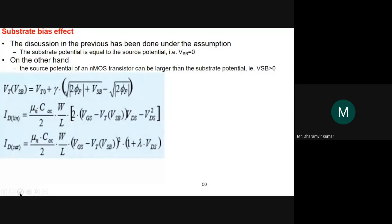So this is the equation for ID in linear mode of operation. Okay, and remember where is this VT, the threshold voltage coming? This is coming here. So if VT rises to a greater value, what happens? This term becomes lesser. If this term becomes lesser, then the overall effect would be such that the current would decrease. Okay, the current will decrease.